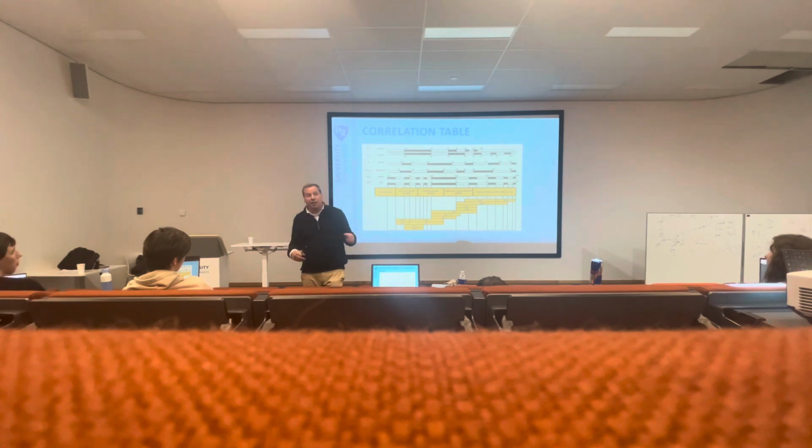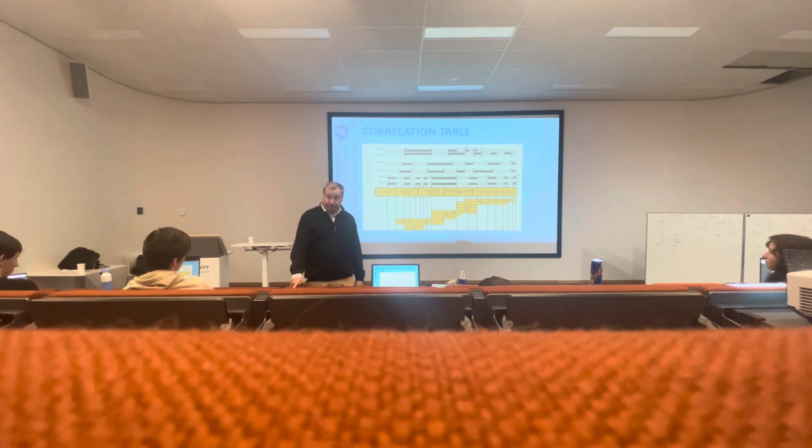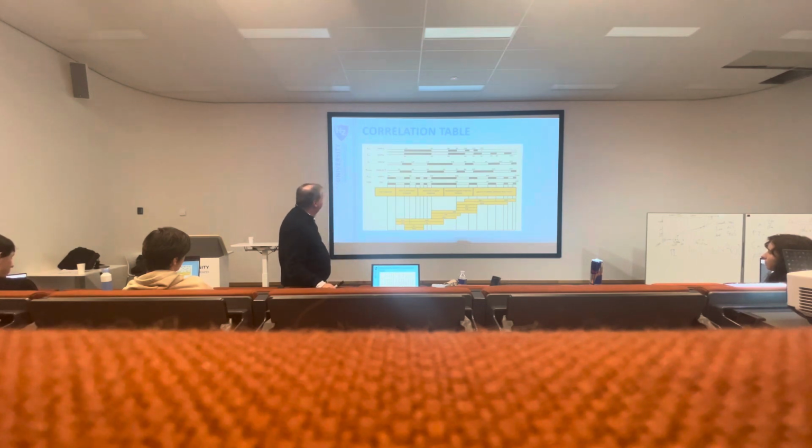In a design they could say we have a sandy subsoil, and then they did lab tests, and out of the lab test the CBR value was 5%. No, not okay. That needs to be checked. Every time you see differences in results, you need to say stop, do it again, show me the results, show me a picture of the sample, because they don't match. You can do different tests, but at the end they should be more or less in one line. So yes, this is very useful.